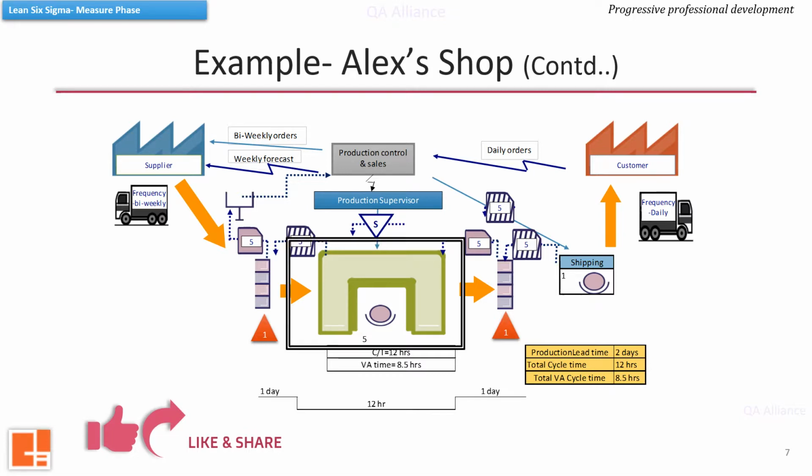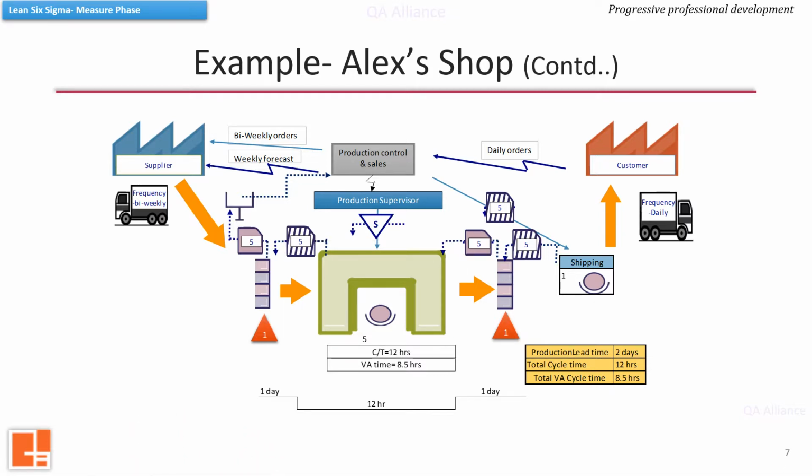Now the shop floor is designed in the form of a work cell, where multiple processes are working in an integrated manner. This will reduce inventory and other wastes like waiting, transportation, etc. The team will also make use of Kanban cards: production Kanbans, to trigger the production of a predefined number of units, and withdrawal Kanbans, to provide instructions to obtain items from the supermarket or previous steps. The inventory will also decrease by taking these measures. Information flow will not be complicated anymore. After making these changes, the estimated lead time will come down to 2 days from the current 16 days.